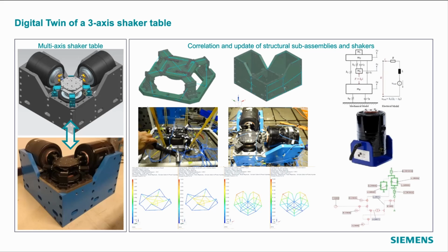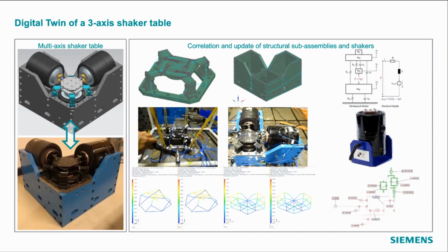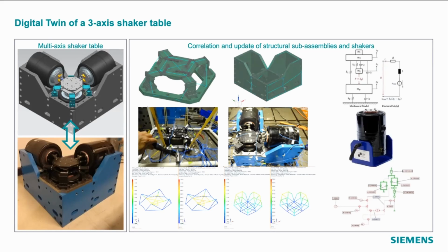So here in this case, we have a 3-axial shaker that is also used, for example, for qualification tests of satellites. As I said at the beginning, you also have these shock responses or random excitations on a satellite when, for example, it is released from the tower at the beginning of launch, or when you have stage separations.